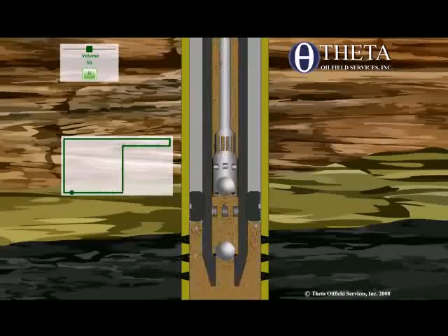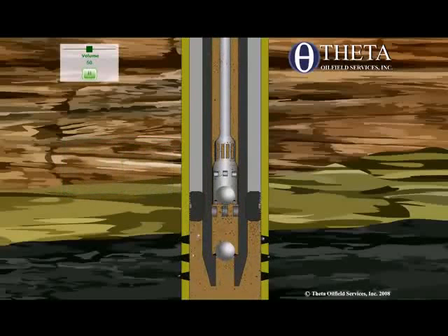Now the pump-off controller, or the rod pump controller, I should say, is going to shut the unit down. And now what happens in the downtime? Fluid level continues to come out of the formation, right? So it builds over the pump until the downtime expires.